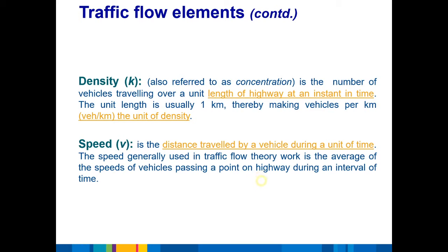To elaborate a little further, if you have an 80 kilometer an hour speed limit, possibly the average speed is 80 kilometers an hour, but the 85th percentile speed might be 85 if you've got reasonably good compliance, in other words, people are obeying the speed limit reasonably well. If you had an 85th percentile speed of 90 or 95, that would tell you that most people are doing the speed limit, but a lot of people are speeding by a wide margin.